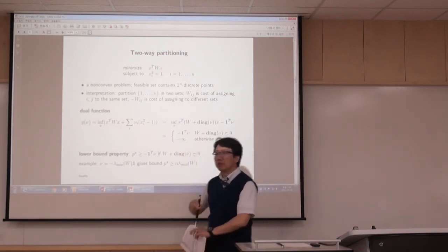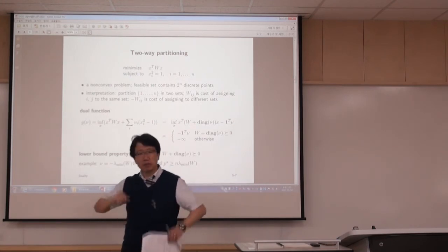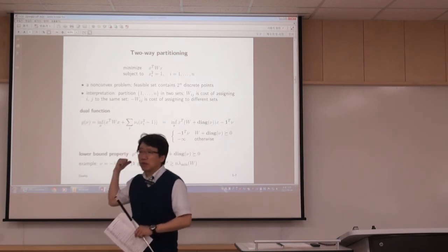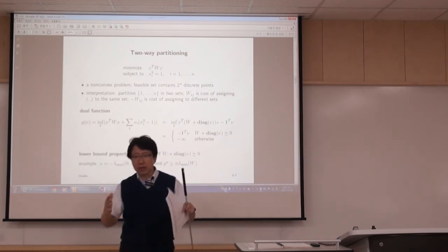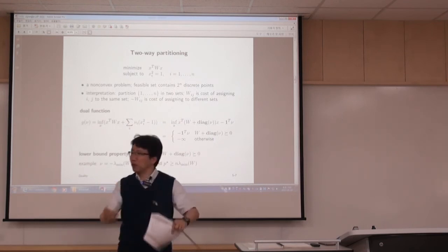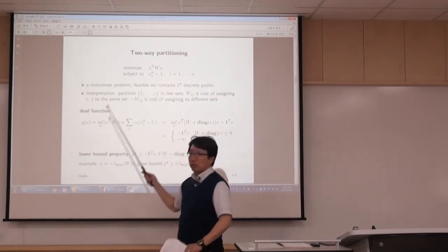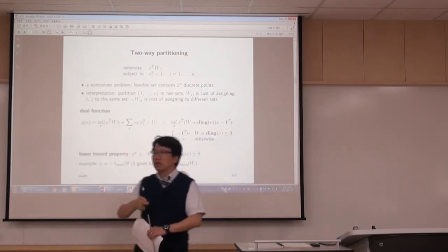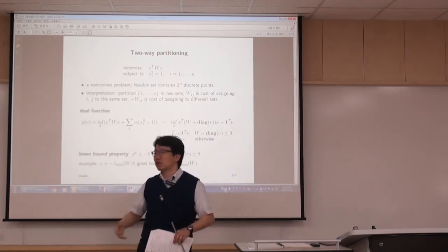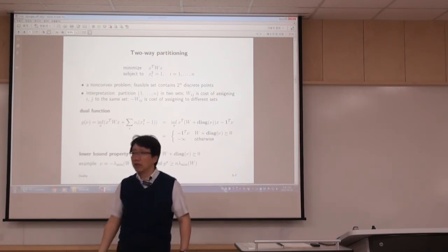This one may be an approximation of peak to average power ratio, for example. In my lab, one of my research assistants solves a very similar problem. He wants to minimize the peak to average power ratio of DFT-spread OFDM or something by PAPR shaping. So this corresponds to the shaping. This W includes the other parameters for the shaping, and X is data. In his case, of course, X is complex valued, so it could be QPSK or something else. But anyway,